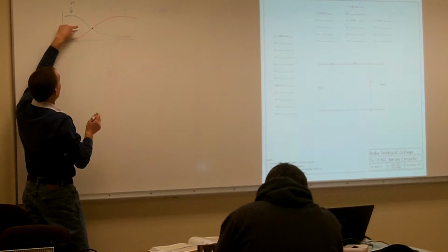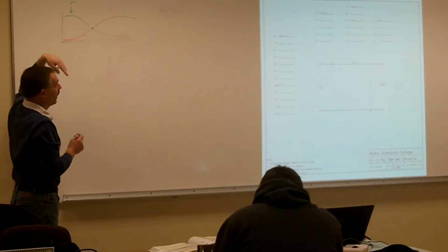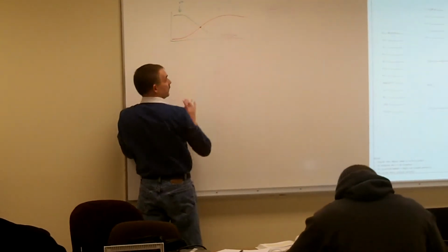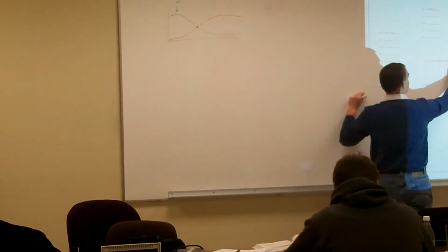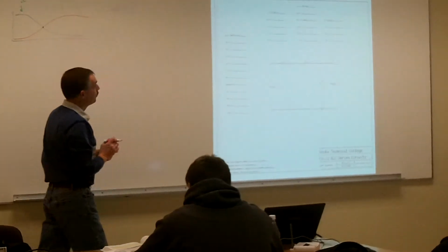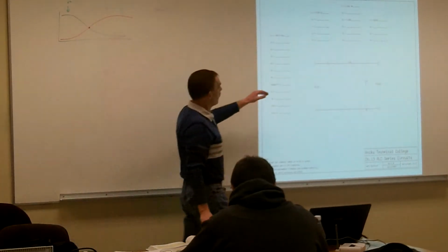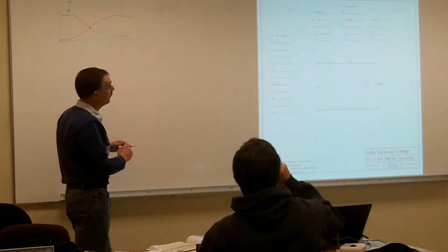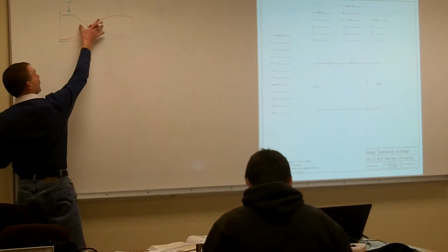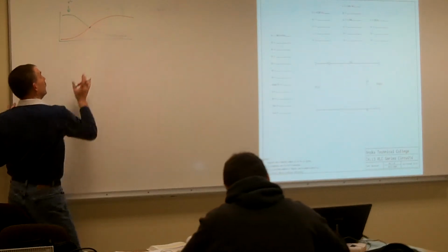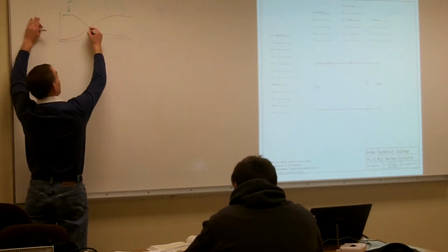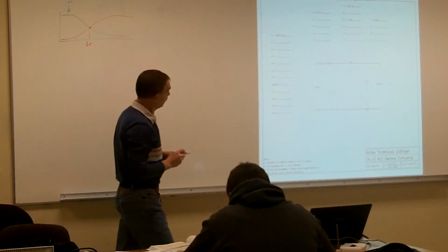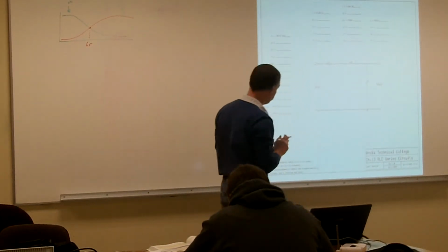This is where X of L and X of C are going to equal, and those two are going to work together. As the inductor is inducing a voltage in our circuit, the capacitor is going to bring in that energy. And when my sine wave starts to drop, that capacitor is going to put the power back into the circuit. So they kind of sit there and cancel each other out. This is what we call our resonating frequency. This is right where X of L and X of C are going to equal.